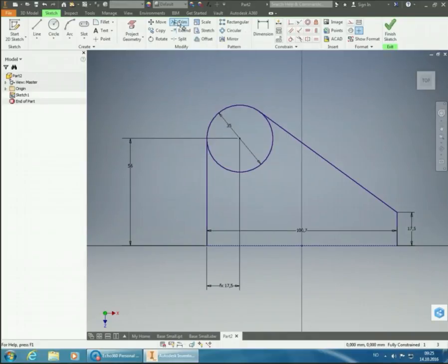We select that one. And now if I move down to the circle, to the area that we want to remove, we can see that it's creating a dashed line between the straight lines. And that means that if I click now, it's going to remove everything that's marked with a dashed line. And it's going to keep the continuous line for the rest of this circle. So I do that. Then we're rid of that one. And now we are ready to mirror it over to the other side.